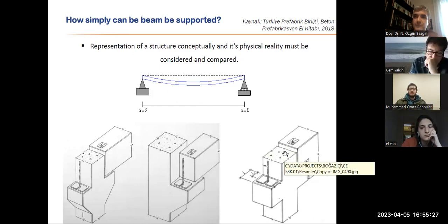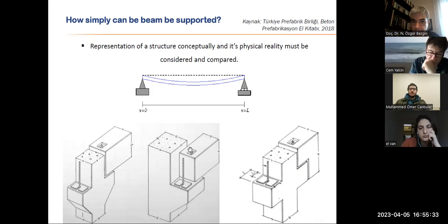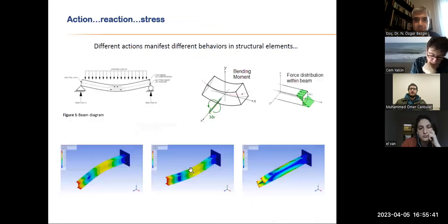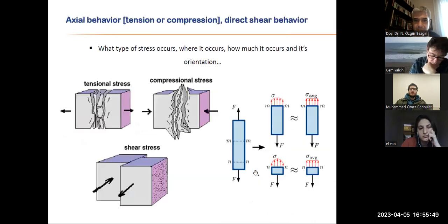These are all verified that if done right, it does function right. But this, for example, does not provide any moment transfer because there's nothing providing the axial forces at the top edges, only shear. So this is a simple support. So we need to visualize the stresses for the bending, for the shear, and for the torsion, and respond to it in an appropriate way.